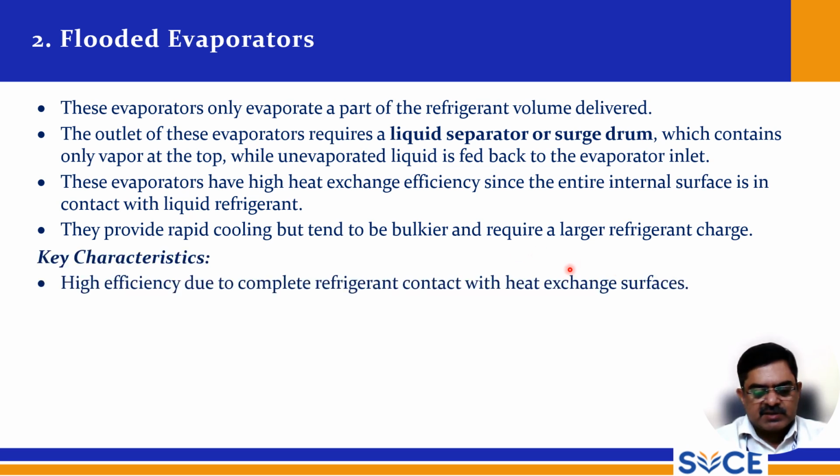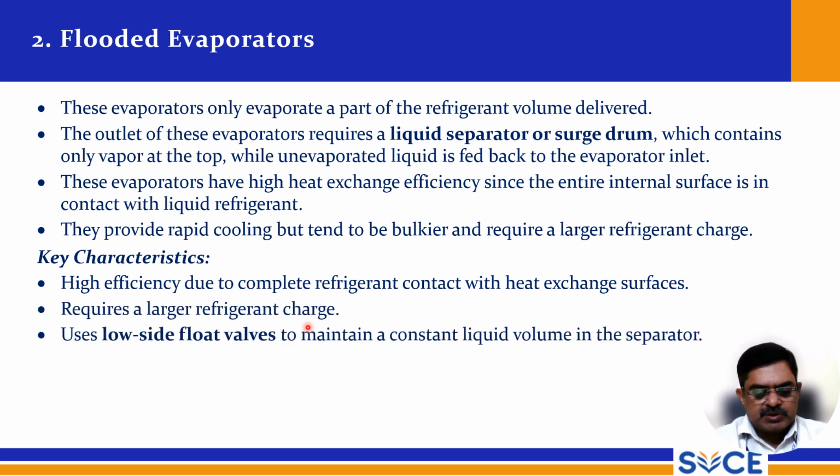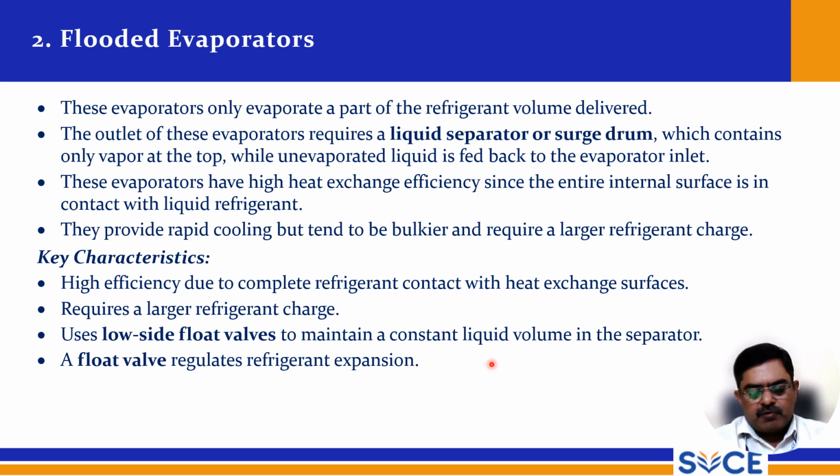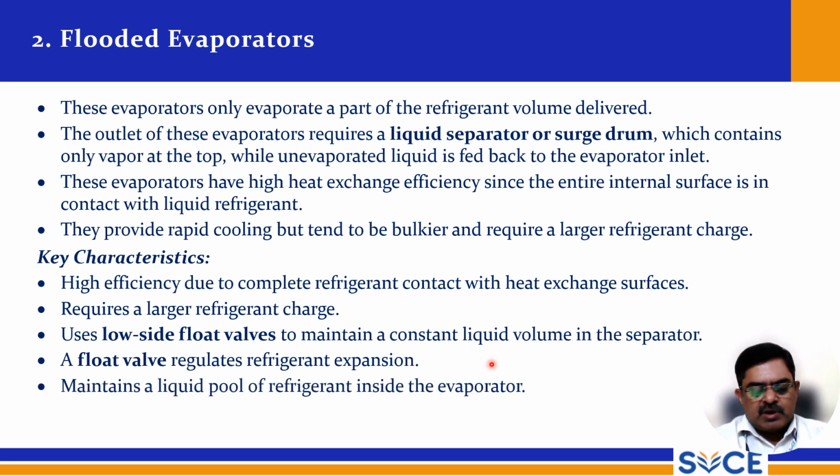The key characteristics of the flooded type are high efficiency due to complete refrigerant contact with the heat exchange surface, it requires a large refrigerant charge, and it uses low side float valves to maintain a constant liquid volume in the separator. A float valve regulates refrigerant expansion and maintains a liquid pool of refrigerant inside the evaporator.